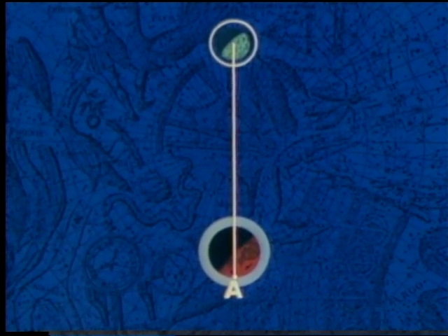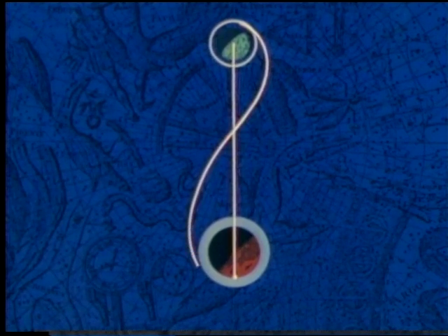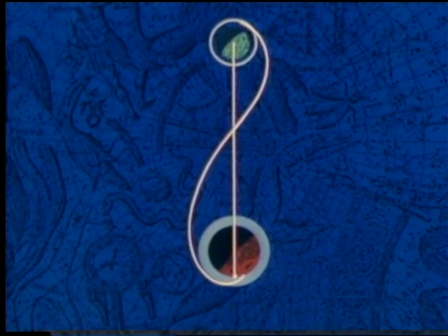To examine these effects and how they act on the return and entry trajectory, we must first define the antipode. A line is drawn from the center of the Moon through the center of the Earth, penetrating the Earth's surface, which faces away from the Moon. The point of penetration is called the antipode, which means simply the point opposite. The return trajectory will pass over the antipode, being determined at the time the spacecraft leaves the Moon's vicinity.